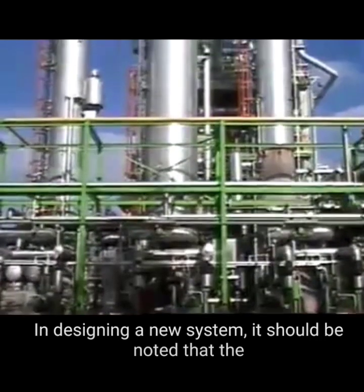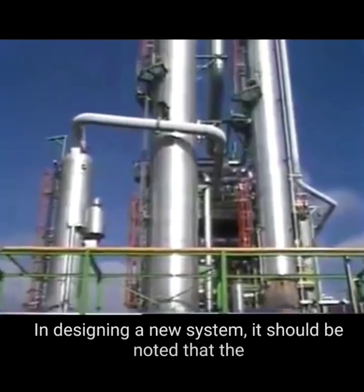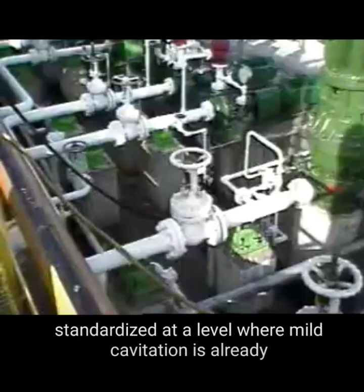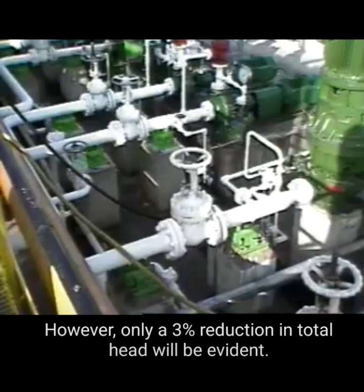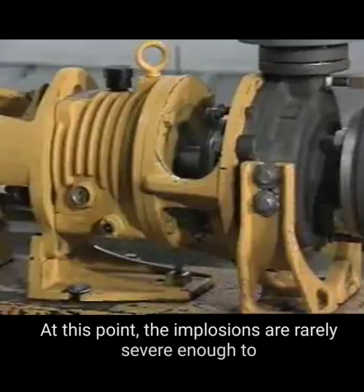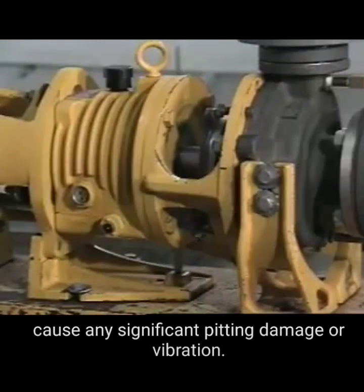In designing a new system, it should be noted that the acceptance measurement of the NPSH required by the pump is standardized at a level where mild cavitation is already taking place. However, only a 3% reduction in total head will be evident. At this point, the implosions are rarely severe enough to cause any significant pitting damage or vibration.